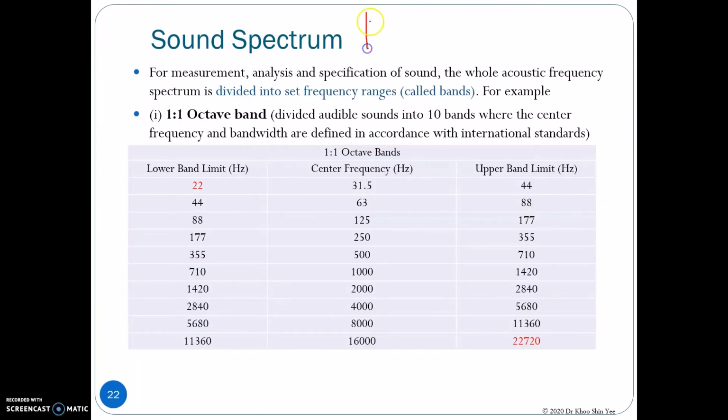For vibration engineering applications, if you have a time domain vibration, after you convert it to the frequency domain, if the vibration here is oscillating, then you should obtain the frequency domain to be various peak data, where each of them represents a single frequency.